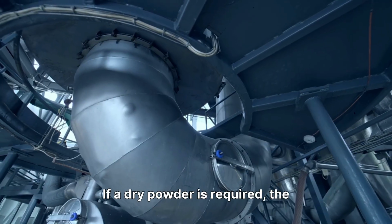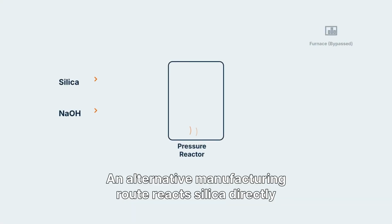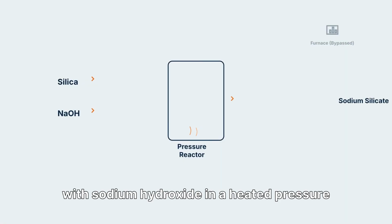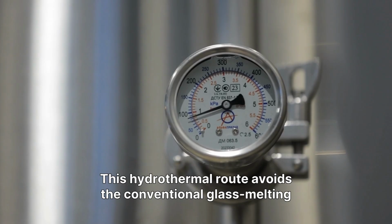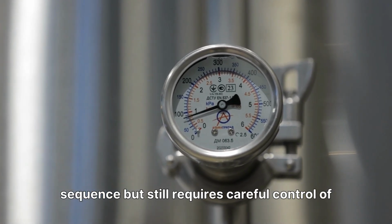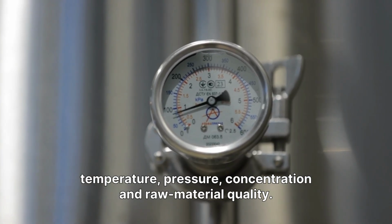If a dry powder is required, the filtered solution can be concentrated and spray-dried. An alternative manufacturing route reacts silica directly with sodium hydroxide in a heated pressure reactor. This hydrothermal route avoids the conventional glass melting sequence, but still requires careful control of temperature, pressure, concentration, and raw material quality.